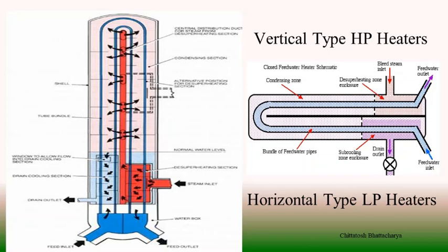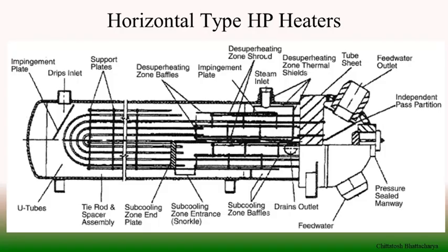To monitor this, it is desirable to carry out a simplified routine performance test on feed water heaters frequently, and this will help in identifying the level of deviation and performance of the heaters at different conditions of supply of steam and feed water within the system.